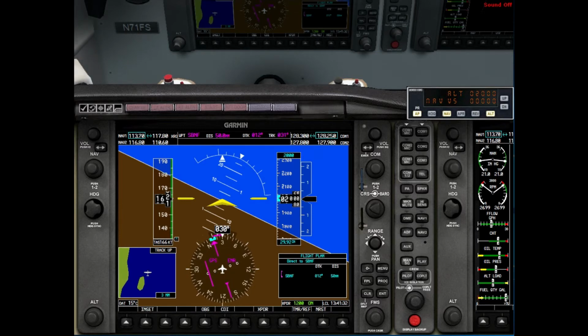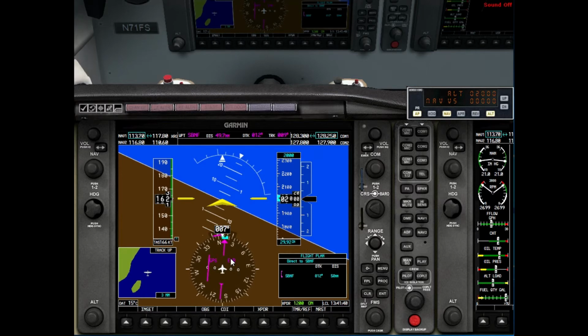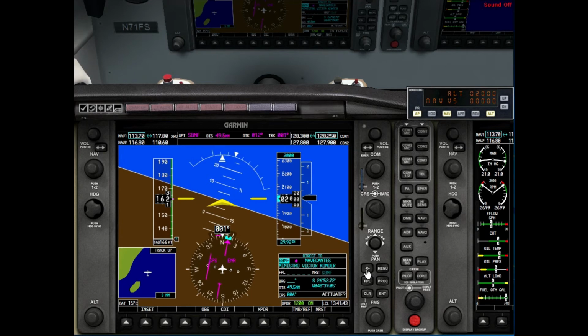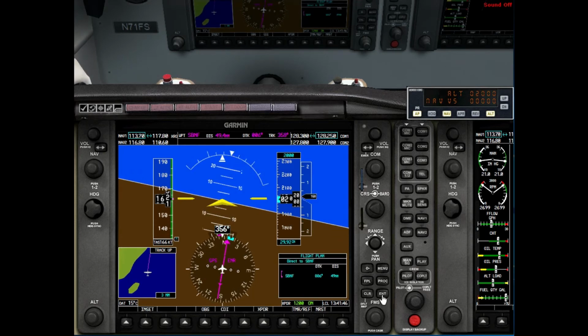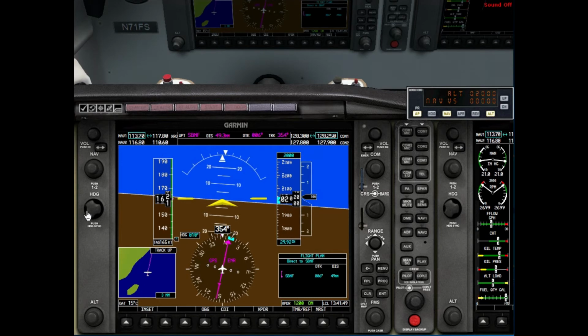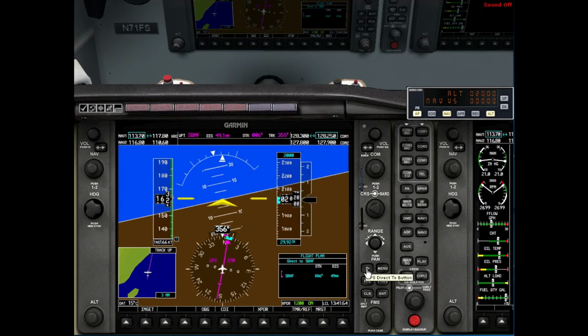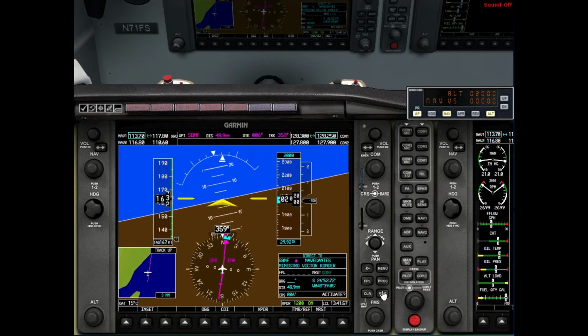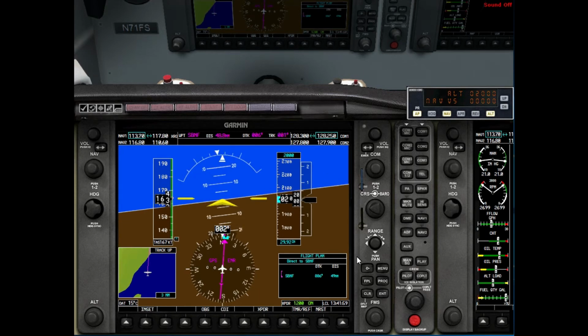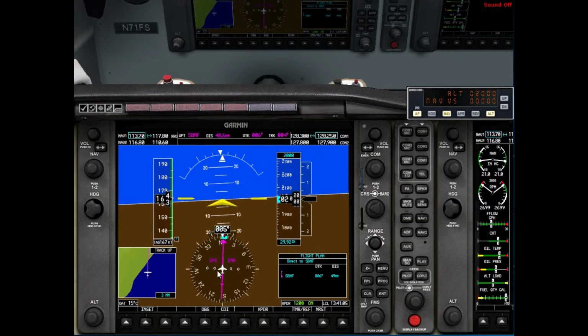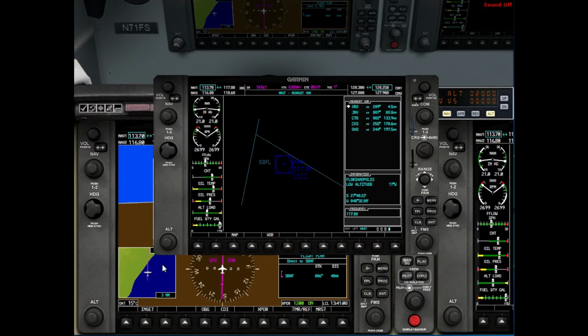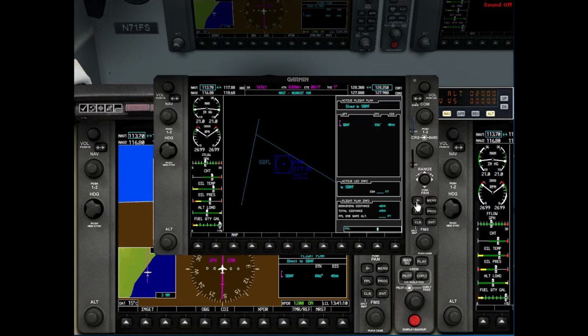As we are using the direct tool, we don't need to make this bar centralized. So what I'm going to do is just put the direct tool again and enter again and activate again. Just to make this centralized all the time, you can put here direct tool, enter again and activate again. The aircraft is going to navigate by itself following this magenta line, as we can check here in our flight plan.